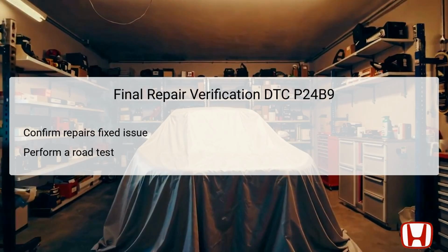Once repairs have been made, it is essential to conduct a final verification to ensure that the issue has been resolved. This involves confirming that the repairs address the root cause of DTC P24B9 and that the system is functioning as designed. A road test should be performed under the same conditions that previously triggered the fault to validate the repairs.